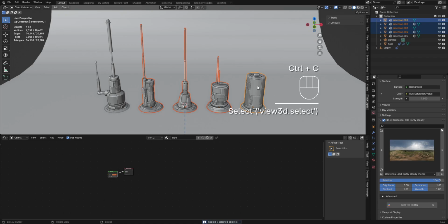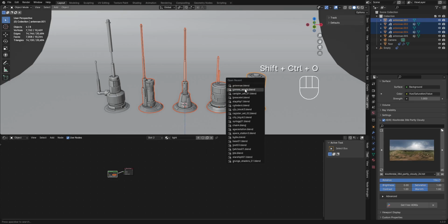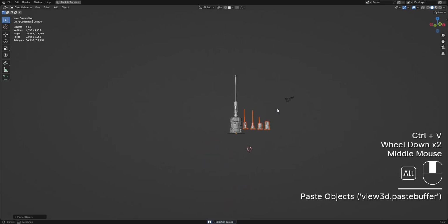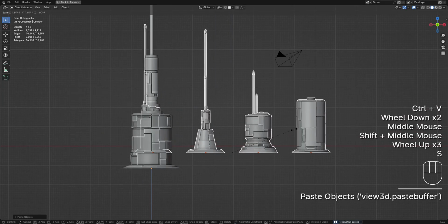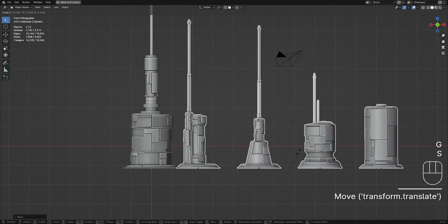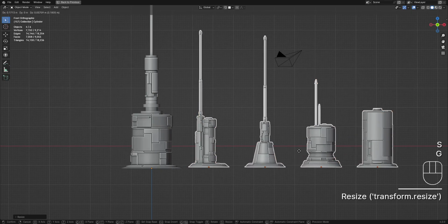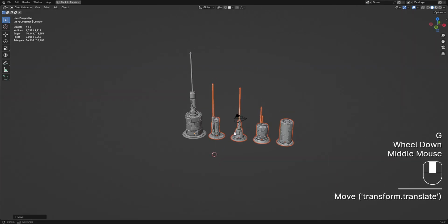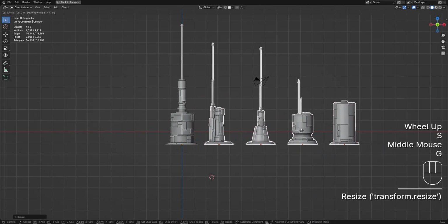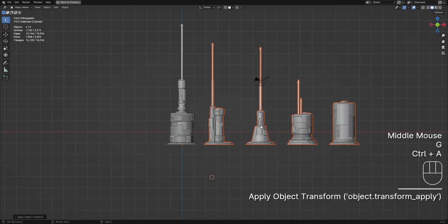When I found out about the Control copy and paste in Blender, it was really good. Control C and then Control Shift O. Open the last file, comps asset. Don't save. Control V, and they are too small compared to the others. Okay, let's bring them up a bit and just apply their location. Okay,